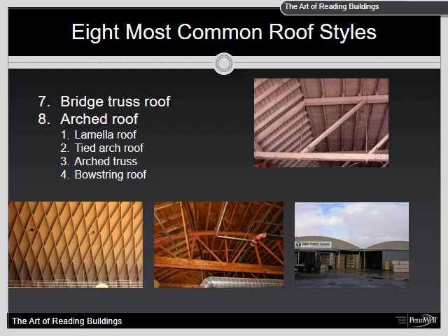Bridge truss roof. The bridge truss roof is a direct descendant of the bridge used to span rivers and gorges for the railroad industry, namely the Pratt truss and Howe truss. The same engineering principle used to support a 40-ton locomotive could also be used to span great distances between walls or columns in buildings. The bridge truss is characterized by sides that are sloped from the exterior wall to a flat roof portion. The sloped sides are derived from the trapezoid shape of the truss.